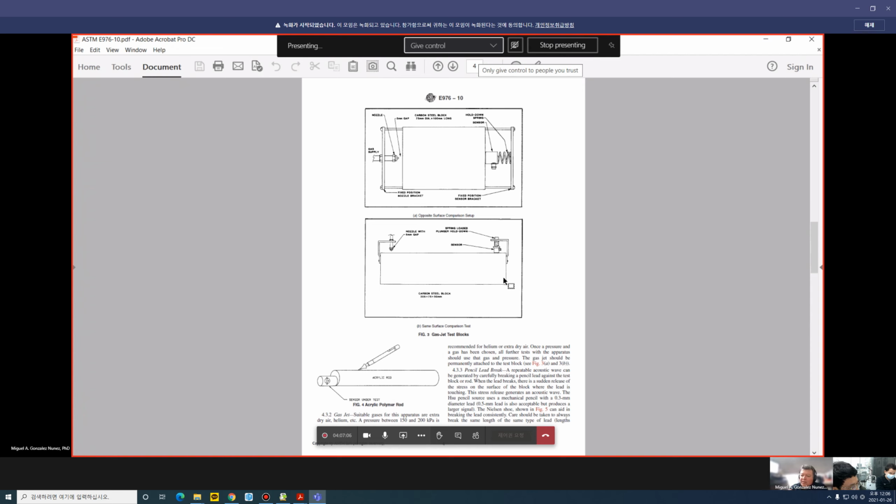Once you know that the wax is solid, then you can let go of the sensor. Then you can do one test when you know the wax is solid, and then maybe use a piece of tape around your test specimen holding the sensor, to see if the amplitude detected by the pencil lead break is bigger or is the same.